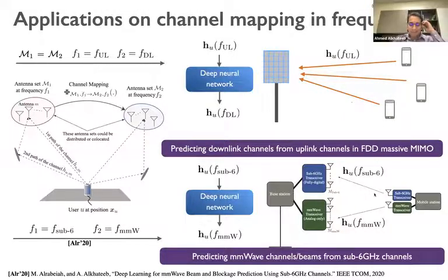Yes, these are excellent questions. For the first one, it's very interesting that some of these sensors could be added in a very transparent way to the standard, let's say 3GPP 5G. If you look at vision or radar, maybe radar doesn't have privacy concerns or challenges. If you augment radar to the base station, it could identify the mobile users that the base station is communicating with, and reduce the frequency of beam alignment, or optimize the codebook, or reduce the size of the codebook.